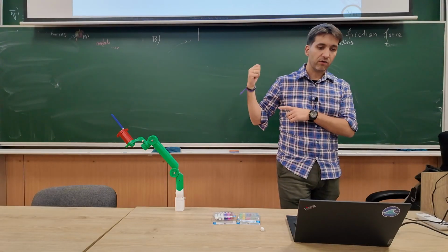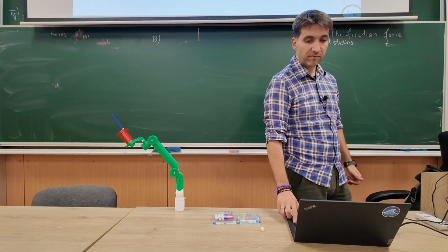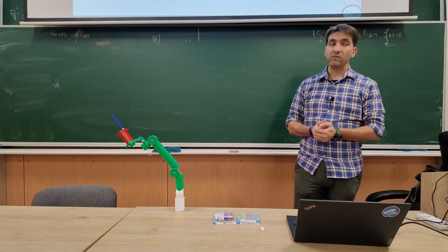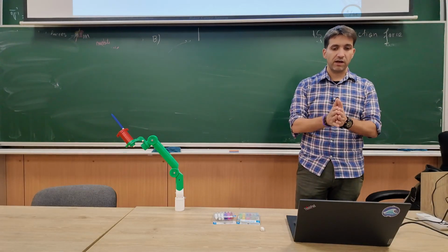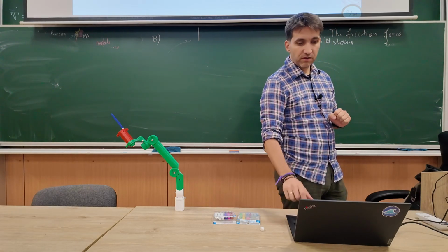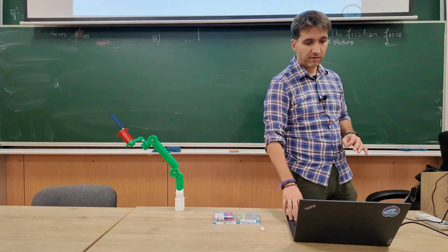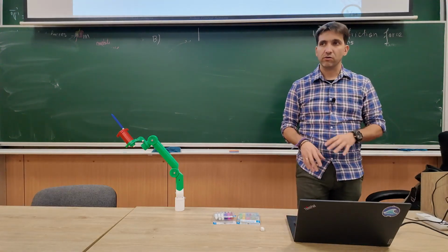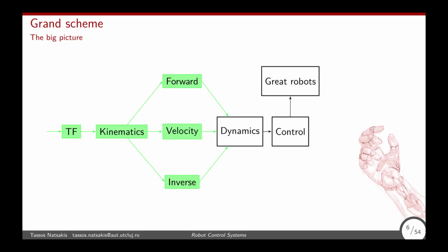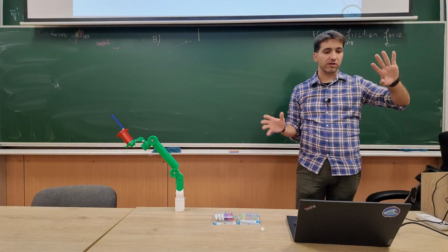So what we did so far: forward kinematics, it's basically this 4x4 matrix, rotation and translation. Jacobian, how we go from joint velocities to end effector velocities, and we'll see that we're going to need these two concepts today to define the dynamic model. So we defined a way to calculate inverse kinematics and velocities, and how we can use this to calculate the trajectories last week. So we did a big part of the modeling, and today we're combining them for the dynamics. What we did so far is all kinematics, and we're going to start talking about dynamics.